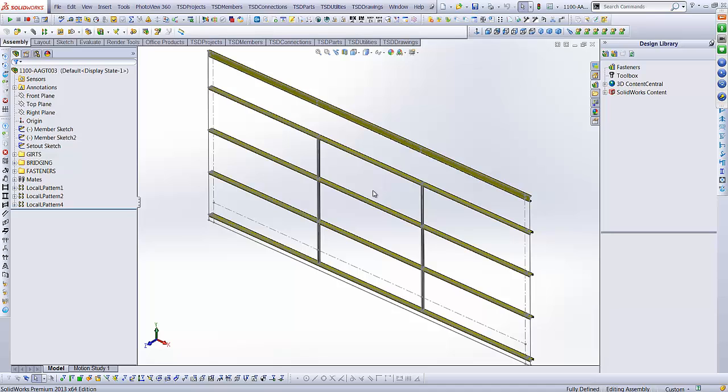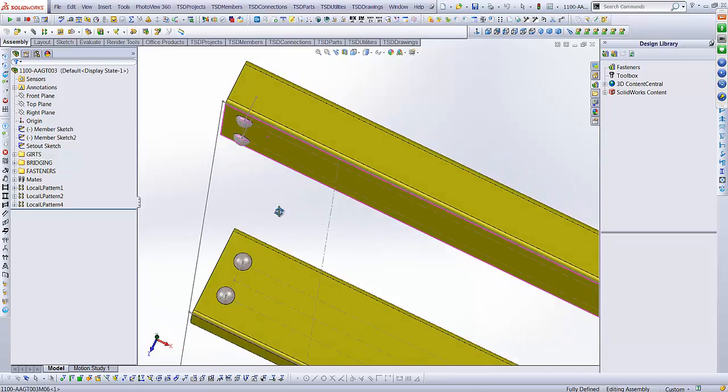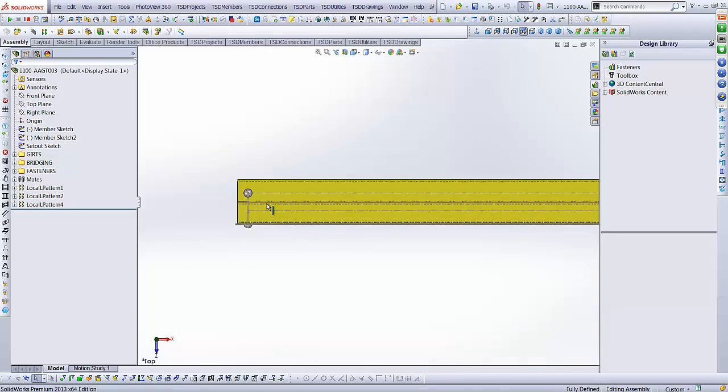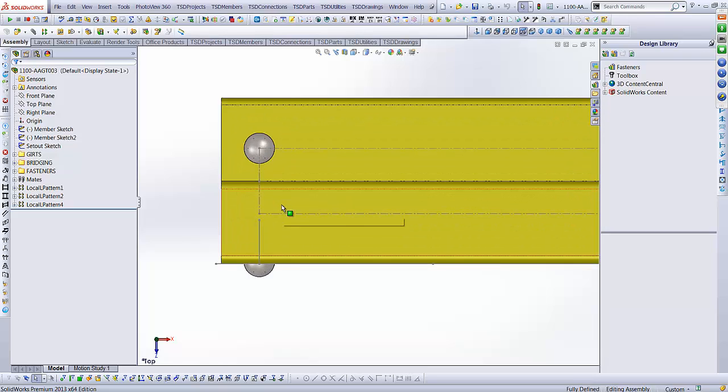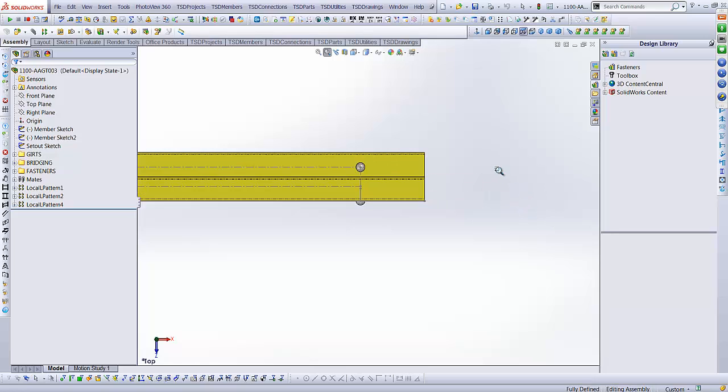The only thing that I need to do now is just prepare the cuts at either end, because this is going to be a centralized bay. So to do that I've got to make sure I've got my 5mm cut at this end, which I do in this case. If I look down on top and take a view, okay, you can see that there's a 5mm cut there. Now on the other end, definitely not. So I've got a bit of work to do down this end.